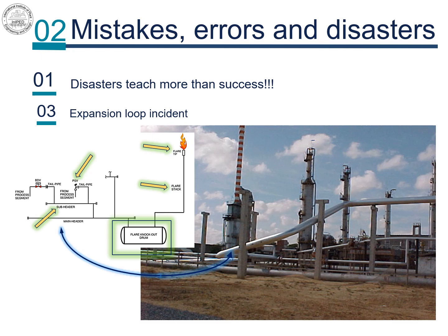Piping shall be evaluated for flexibility and expansion loops shall be provided wherever necessary. Expansion joints shall be avoided. Flare piping loops are planned in the horizontal plane, 2D bends, in order to ensure pipe slope for free draining requirement. From this angle, it looks like that due to large thermal growth of the horizontal section before the expansion loop, pipe movement simply exceeded the available sliding space.